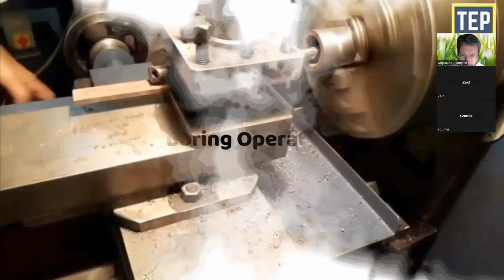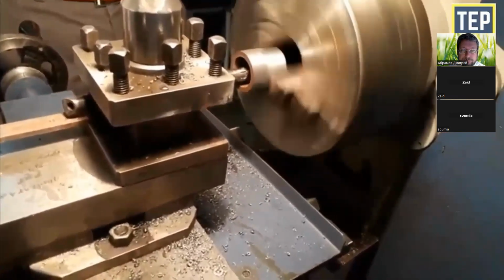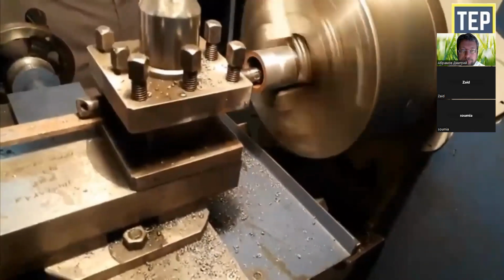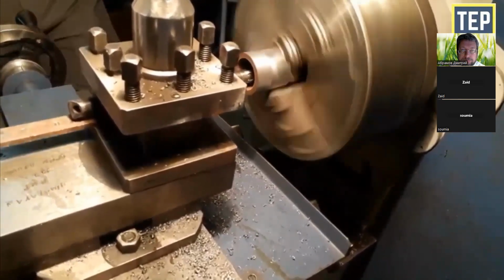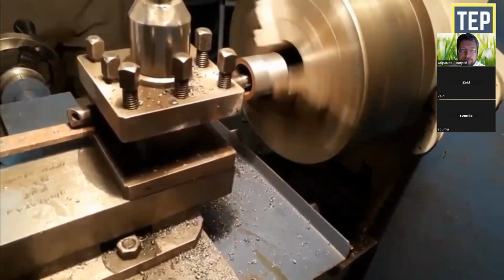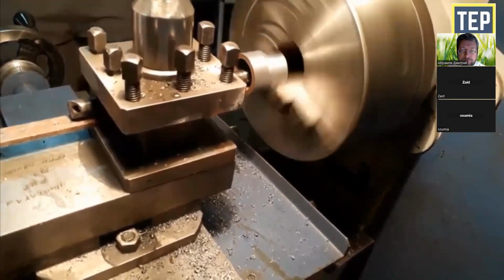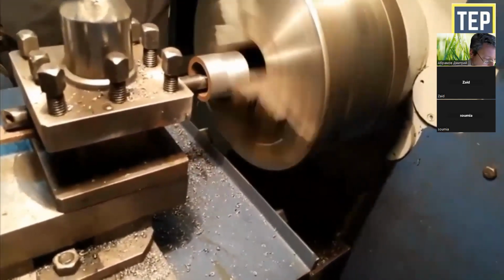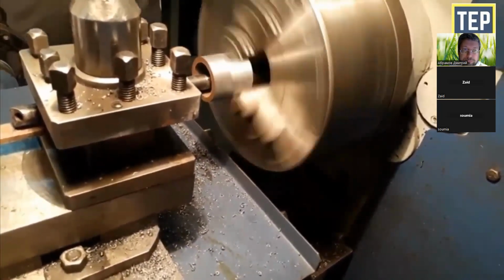Boring operation. Boring is the operation of enlarging the hole, which is already drilled, punched, or forged, and it cannot produce a hole. In this, the workpiece is revolved in a chuck or a faceplate, and the tools which are fitted to the tool post are fed into the work. It consists of a boring bar having a single point cutting tool that enlarges the hole. It also corrects out of roundness of the hole. This method is adopted for boring small-sized works only.